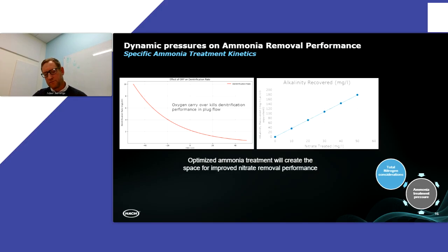You can remove the nitrate, and that removal of nitrate can help reduce the organic load then going through your aerobic zone. So you don't have to remove those same organics oxically when you have, say, a total nitrogen limit or a total inorganic nitrogen limit.